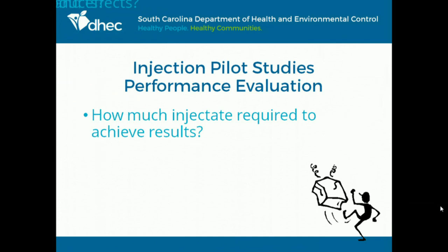For instance, do you stall out at vinyl chloride, and you can't get past it, and all of a sudden you have all this vinyl chloride accumulating? I think that's a good thing to know before you do that on a full scale, that we can't get rid of our vinyl chloride. We need to look at another technology. For zero-valent iron, sometimes you need to have enough of it, or you will also create vinyl chloride. If you just have too little zero-valent iron, it can be a problem.